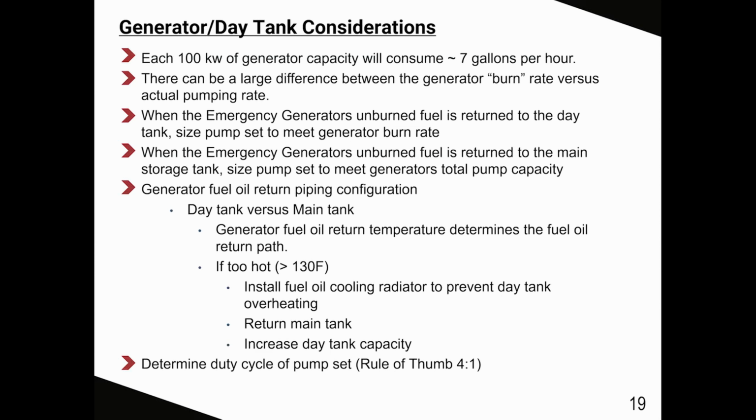Then you determine the duty cycle of the pump set. Typically, on taller buildings, the rule of thumb is 4-to-1. And this could be buildings at 30 stories up. Sometimes with 3 or 4 or 10-story buildings, you may only use a duty factor of 3-to-1.